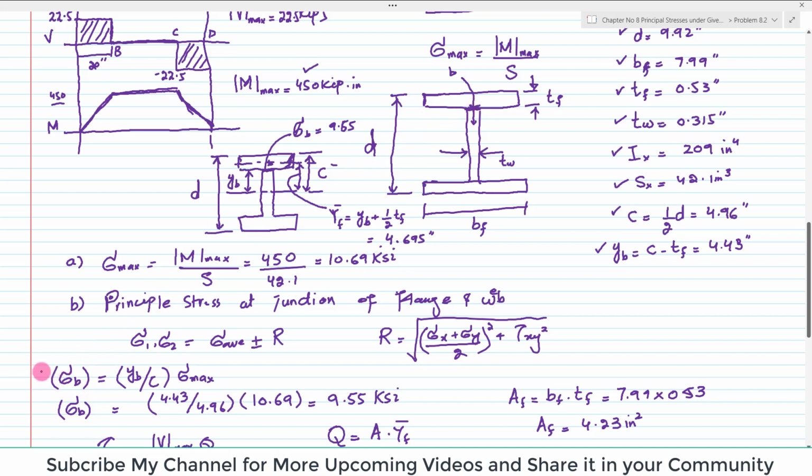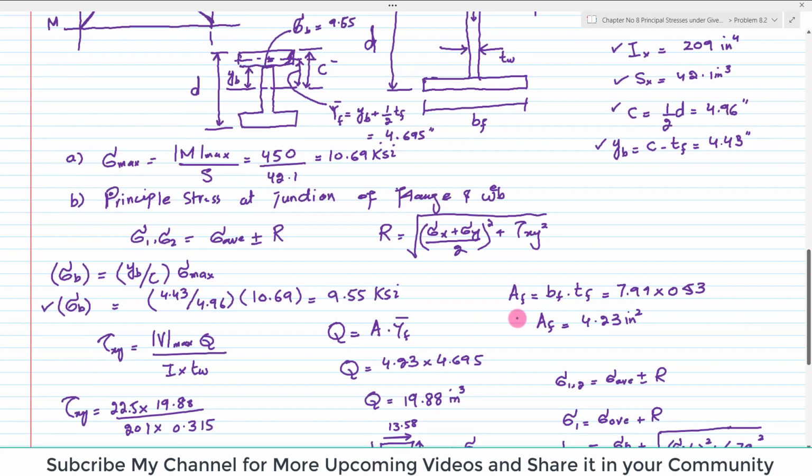So the stress at point B will be equal to the ratio of YB over YC. What is YB? YB is the distance from the neutral axis to the junction point, and YC is the distance from the neutral axis to the outermost surface. So YB over YC times sigma max will yield sigma B. We have put in the values and calculated sigma B, which is 9.55. Again, this is explained thoroughly in problem 8.1, but I am explaining it again.